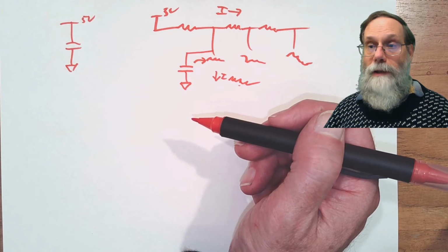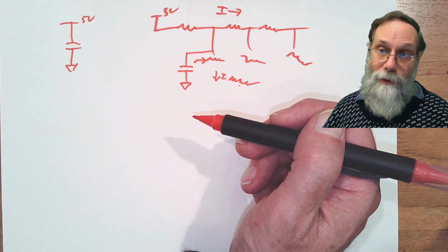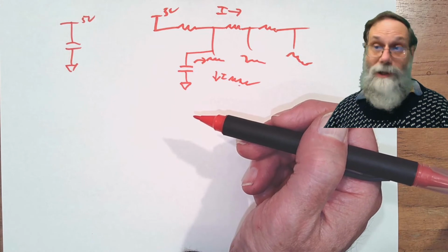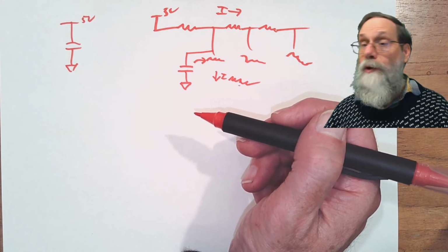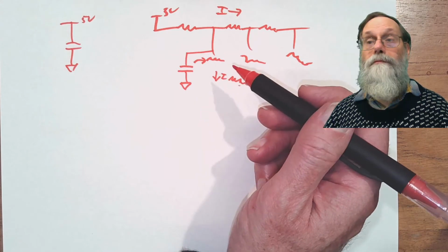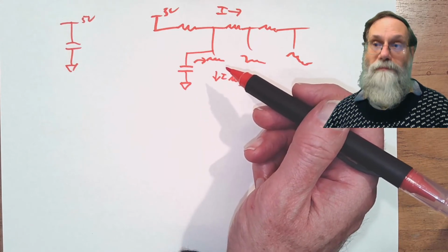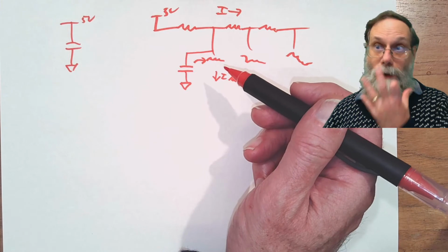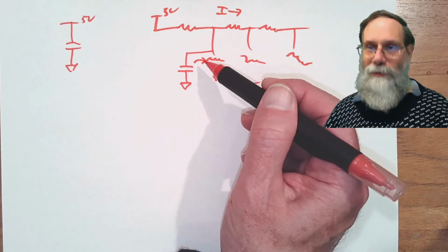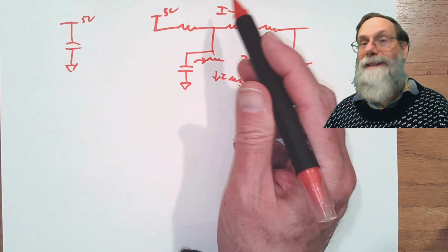They protect the chip from fluctuations in the power supply, and they protect the power supply wiring, which is to say the other chips, from fluctuations in current that this chip takes. It's like wearing a mask for COVID. It not only protects right where it is, but it protects everyone around it.